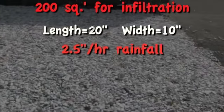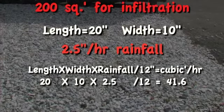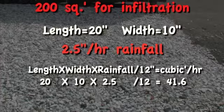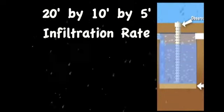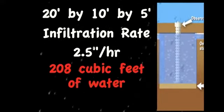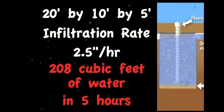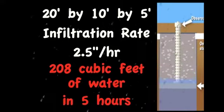At a rate of 2.5 inches per hour, this can be expressed as length times width, or 200 square feet times 2.5 inches per hour divided by 12 inches equals 40 cubic feet per hour. A 20-foot long by 10-foot wide by 5-foot deep infiltration device with an infiltration rate of 2.5 inches per hour can be expected to treat 208 cubic feet of water in 5 hours, well within the required 72-hour drawdown for an infiltration device in the District of Columbia.